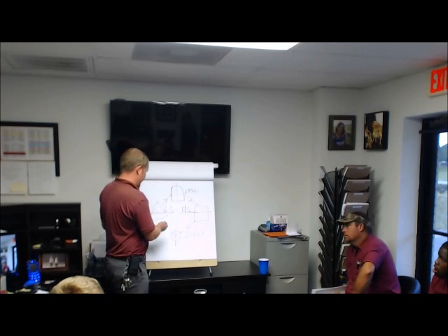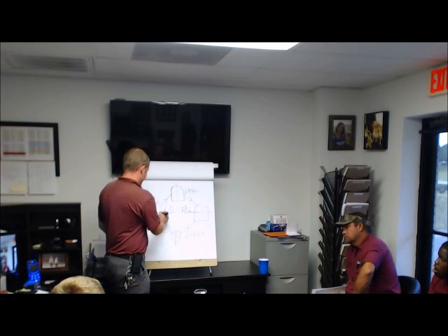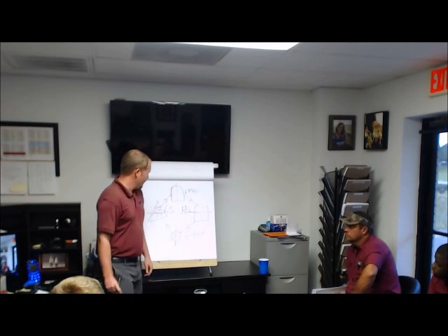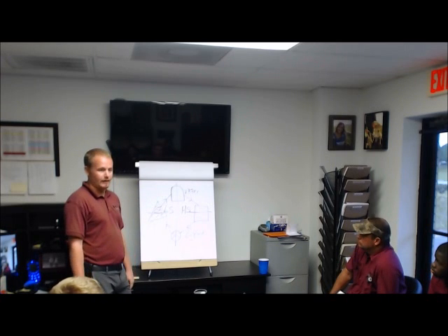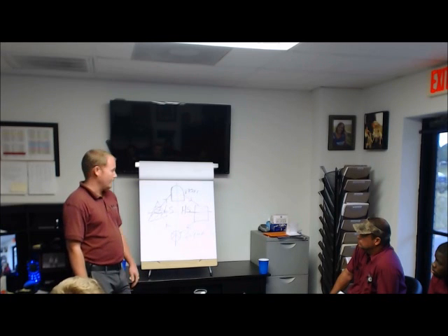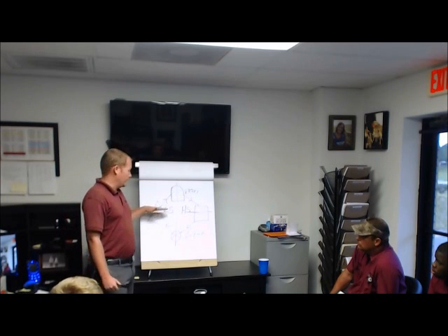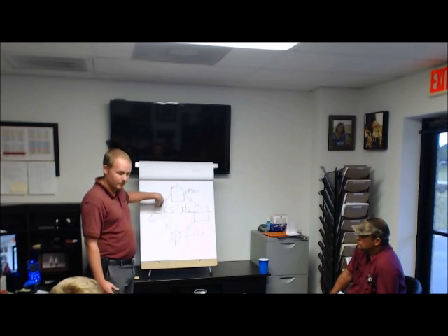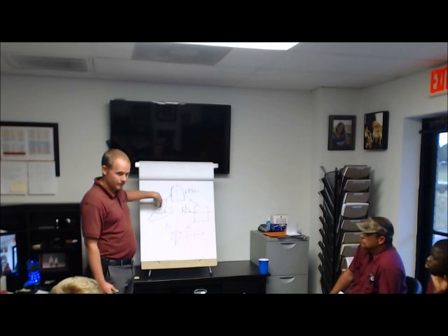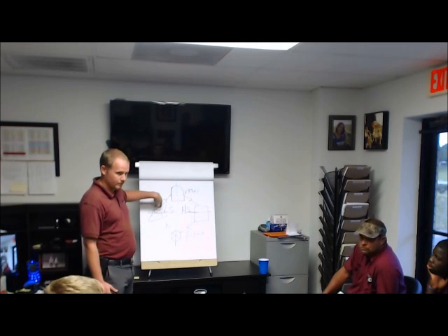Now let's say this is our evaporator coil here. And it's here and here and here and here. It's got all these tubes feeding in, and then it hits the suction line. How far through this evaporator coil do we want to see it changing state from liquid to vapor? You want to use the whole coil. Yeah, throughout the whole coil. Well, if your whole coil was change of state, then what would your superheat be right here? Yeah, I mean, you don't want it to come out the other side, but you want it to fully change state probably 3/4 of the way through the coil.